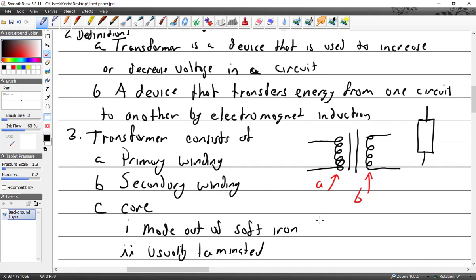So when we talk about doing non-destructive testing with magnetic particle, you can magnetize a crankshaft, it stays magnetized, and you can work with it in your medium and inspect it without giving it more current. But with a soft iron core, you have to run the current through the part while you're applying the medium, because as soon as you remove the current, the magnetism dies off.